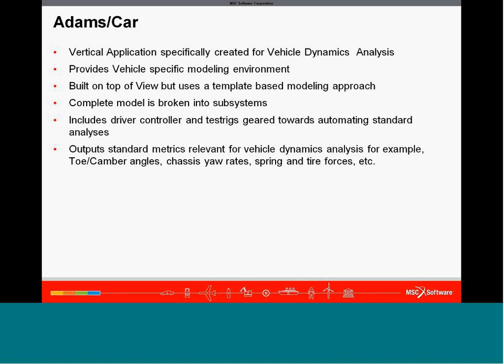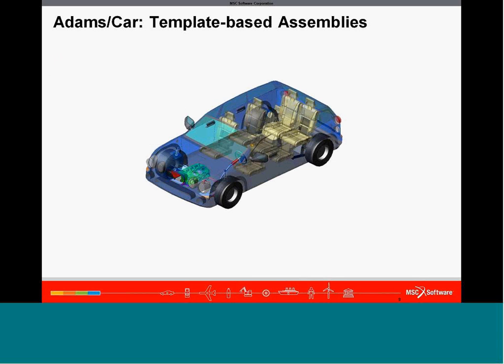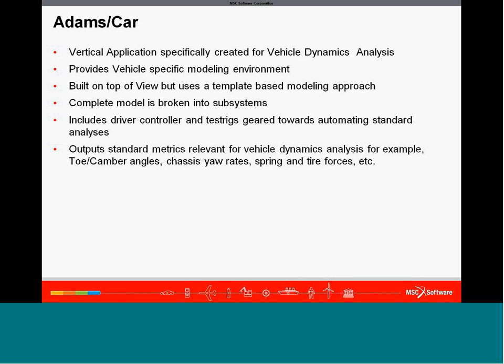Its main logic is that it's a template-based approach. That means things are broken down into subsystems, and then, like building blocks, you assemble the model together. It also has things like a driver controller to drive the vehicle around. In the previous examples, we were creating motion statements or force statements to actuate the model, get it over the bump, have it turn, etc. It also has standard metrics, things like the toe angle calculation, camber angles for suspension analysis.